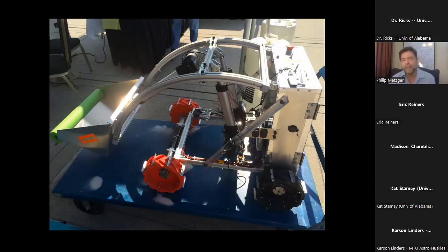Another way, maybe you don't chain the front and rear together, but have really good slip control, so that if a wheel begins to slip and the torque goes down while it's maintaining rotation, then you back off the torque on that wheel and increase the torque on the other wheels. So having really good independent wheel control is another way to avoid that diagonalization from happening.